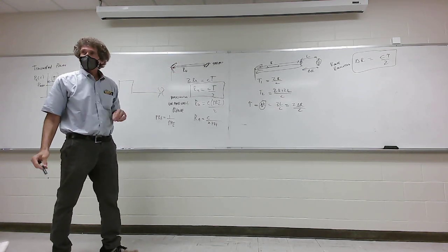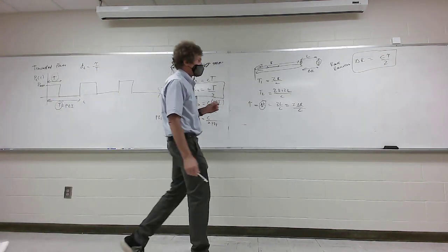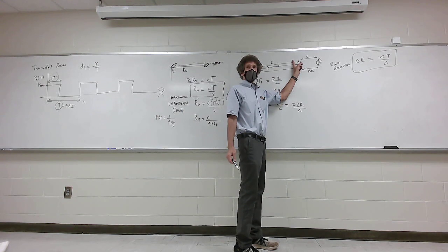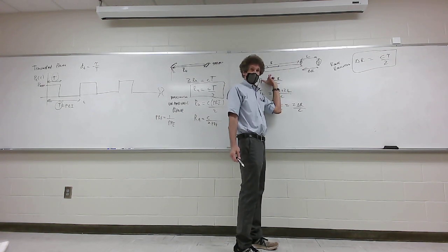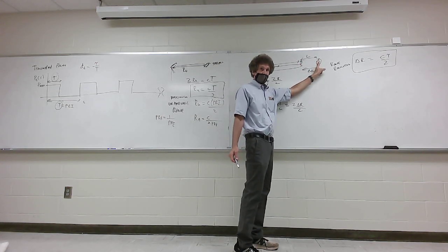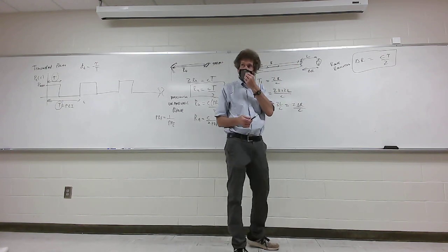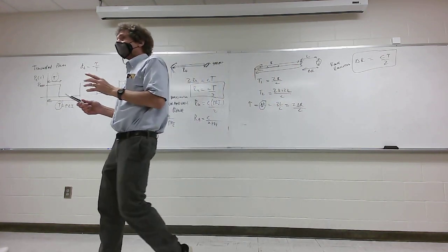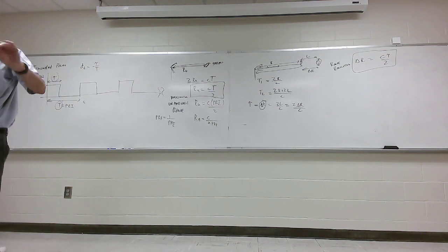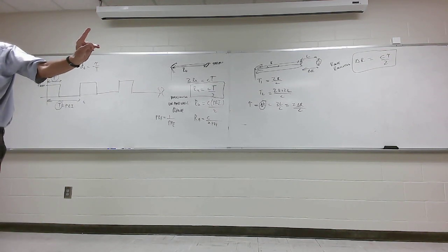Now you can go through the math on this one, but you'll find that the minute the on time is longer than this value, the signal reflected from here will still be present when this one starts coming back. And you can't tell which signal is reflected from what point. All right, so that's how that delta T enters in terms of being able to differentiate different reflective points.